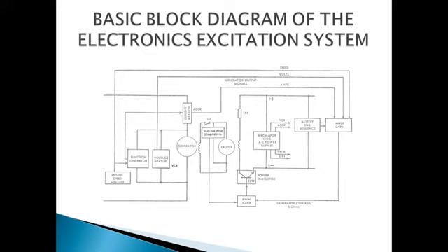The excitation system also ensures that the electrical limits required for the safe working of the alternator, that is, the maximum current or voltage, are suitably imposed. The excitation system controls the exciter field current, in turn controlling the exciter output, which feeds the traction generator or traction alternator field. Thus, the traction alternator output is suitably controlled.